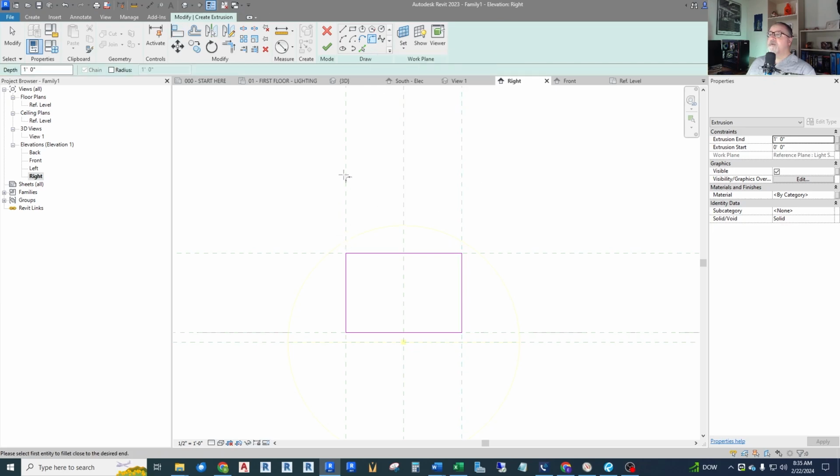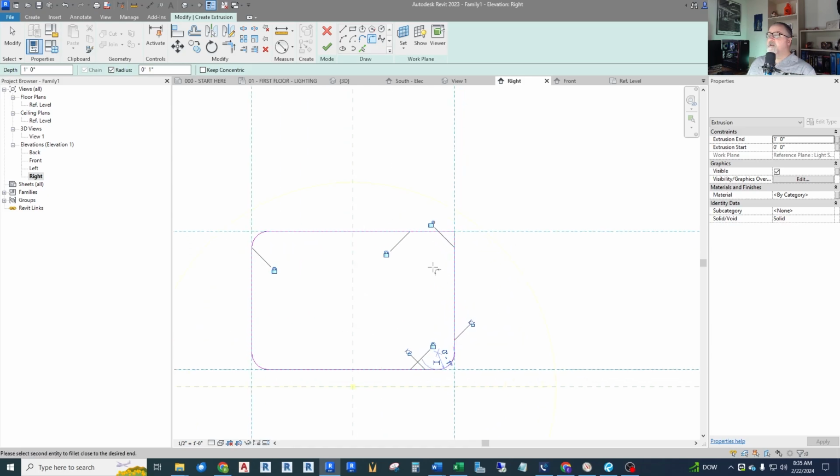I'm still in sketch mode. Now up here, in little tiny words, we've got a depth and we've got a radius, 1 foot radius. Well, in this fixture, if it's going to be like a 2-inch tall fixture or something, I don't want my fillet that big. I guess the thinnest fixture I might have is 2 inch. So I think a 1-inch fillet should do it. So 1 inch, click there, and it rounds the corners as you can see. And it's locked because I had already locked this sketch. Here, and we'll just continue to fillet these corners. And I missed one, try it again, there he is. So escape out of there.